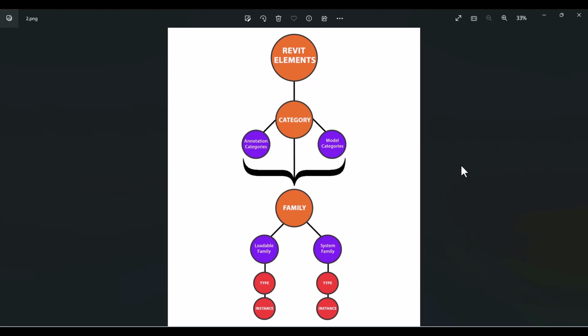When we need, we can make lots of models and types of our system families. That type of system family has some parts or elements that are useful in our project. For example, we can make some changes in edit type of a wall, duplicate and copy it, and make a new type. So we have a free hand here to make our favorite kinds in system families.